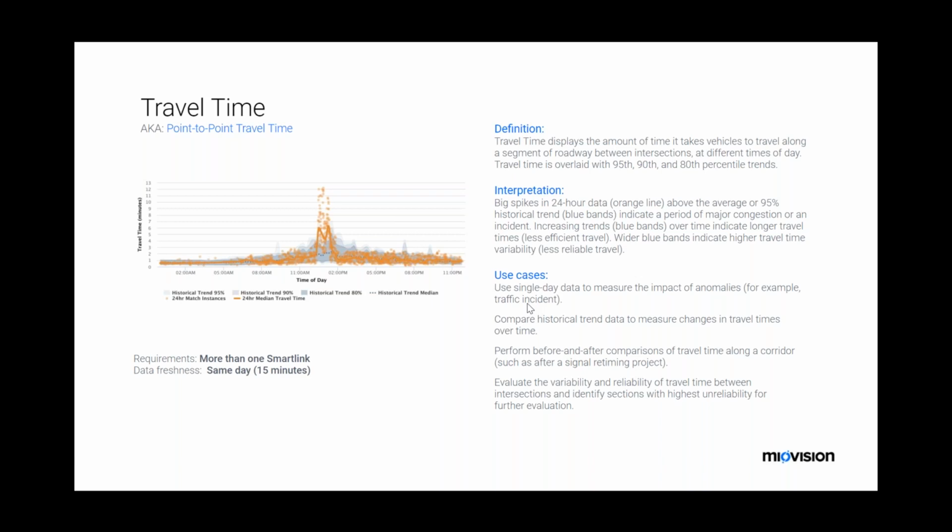And then it plots them on a chart so you can see throughout the day what the general travel time is. It being a Wi-Fi mechanism, the yield rate of this data is typically around, I would say, 10 to 16%. Most people have Wi-Fi on their phones. Most people are utilizing Wi-Fi in some way. That's why we chose to use Wi-Fi over Bluetooth. But that means out of all the traffic on the road, we are still capturing about 16% of all those vehicles, which gives you a representation of what the general traffic is. It's not the whole picture, but it certainly gives you enough of the idea to look at an overall trend.